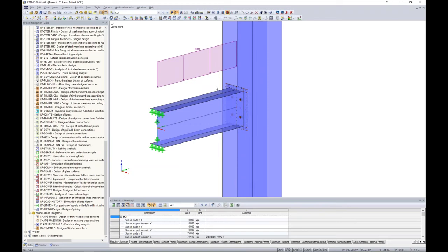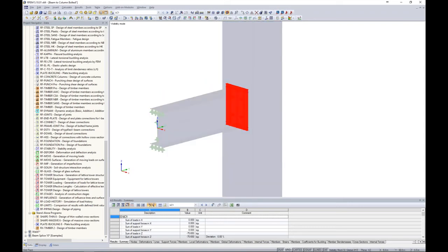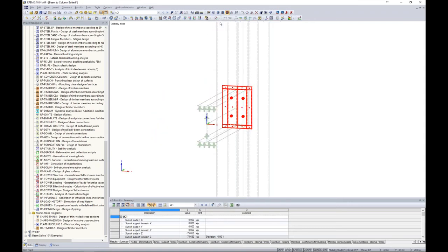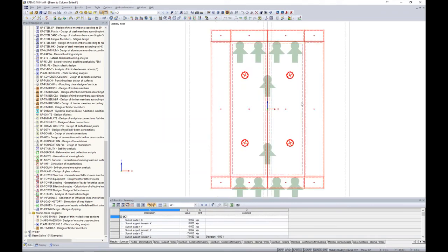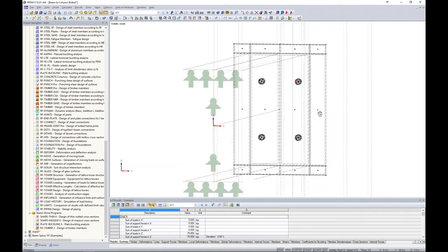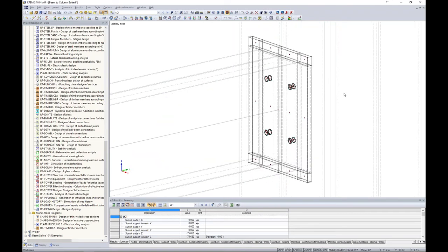Again, we don't have symmetry on the left and right-hand side of this plate anymore. So making a visibility view here based on my plate only, and maybe I turn this into wireframe, and we'll change around the viewpoint here. Here is my plate looking into the page of my beam. You'll notice that I have 4 contact solids defined at the top, 4 in the middle, and 4 at the bottom. And the reason for this is simply because I didn't have so much symmetry like we did in our last model, that I had to create these smaller contact solids in order to meet the requirements.